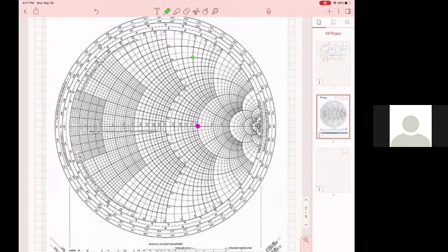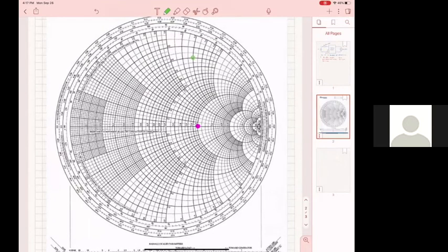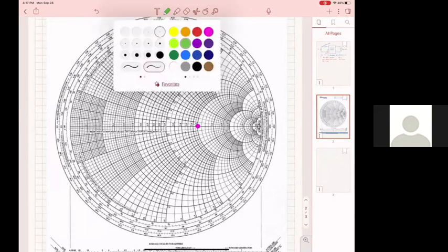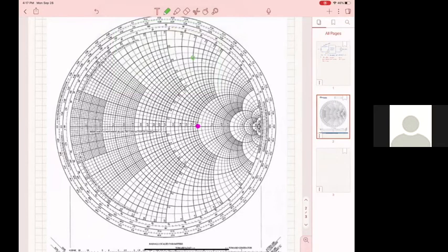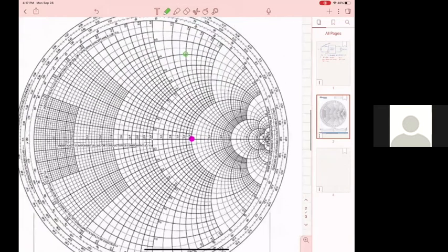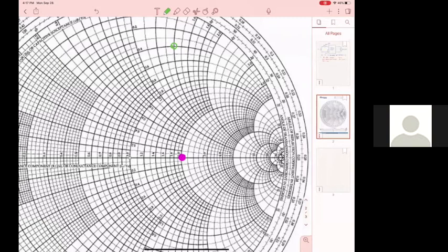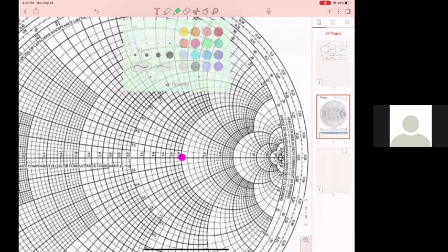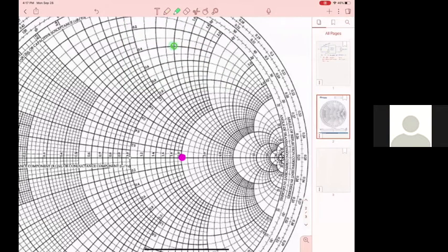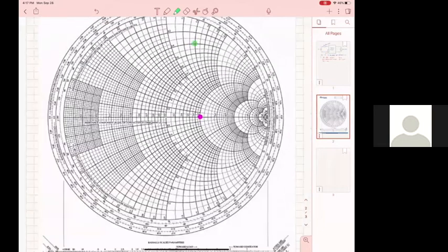Usually, as you can tell, going around the Smith chart along a transmission line is not going to do it, because they don't have the same distance from the center. So if I were to draw the constant VSWR circles, they're not on the same VSWR. Exactly.